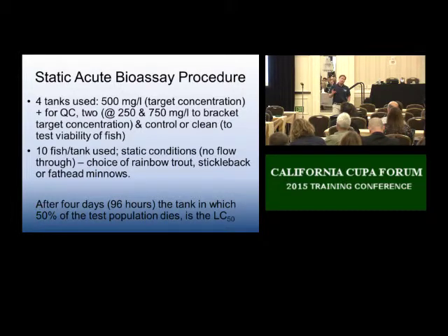Corrosive. This one's a little different between state and federal. Let's go federal first, RCRA. Does the material that's aqueous, meaning the material contains free liquids, which is water, have a pH at or below 2, which is acid, or at or above 12.5, which I'm going to call alkaline or a base? Is it at the low end of the pH scale or the high end? I'm going to consider those aqueous materials that I'm disposing of as a waste a hazardous waste because it exhibits a corrosive characteristic. It'll probably cause irreversible problems to tissue.